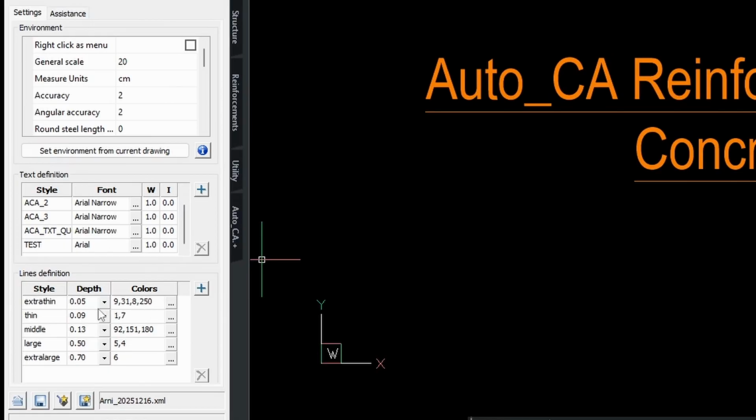One important rule is that the same color cannot be assigned to more than one line weight category. If a color needs to be moved to another category, it must first be removed from its current location. Otherwise, the dialog will not allow the configuration to be saved, since a CTB file can associate a color with only one line weight.